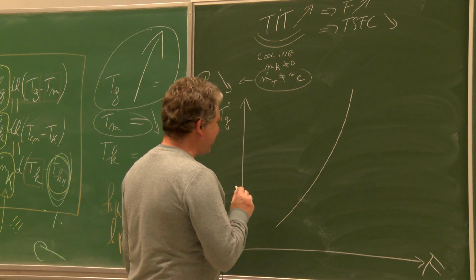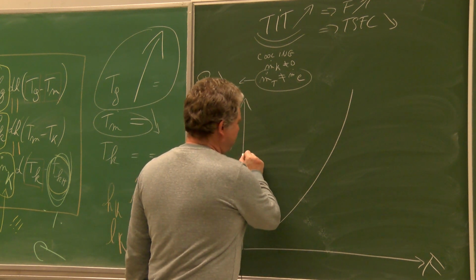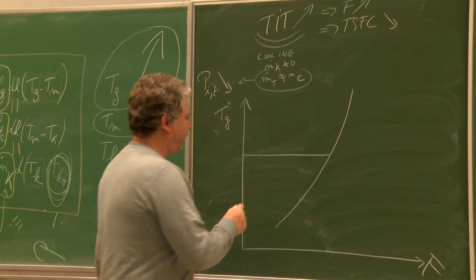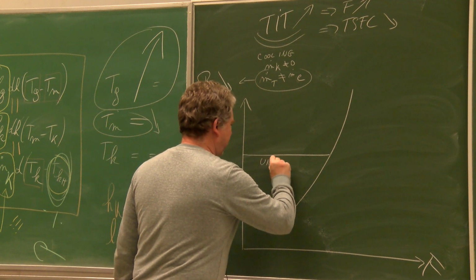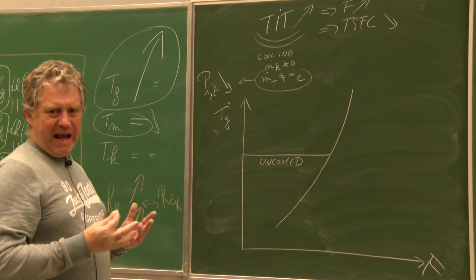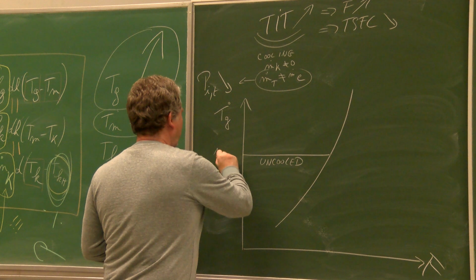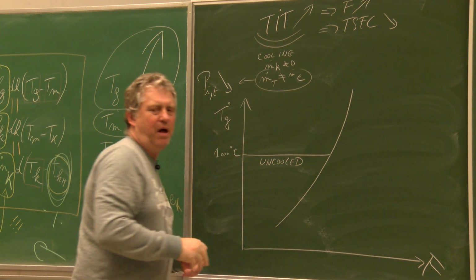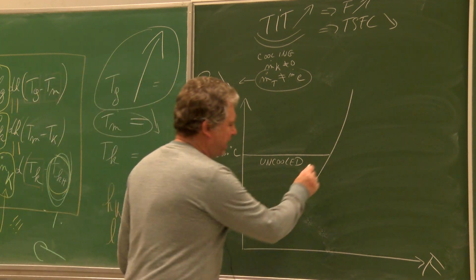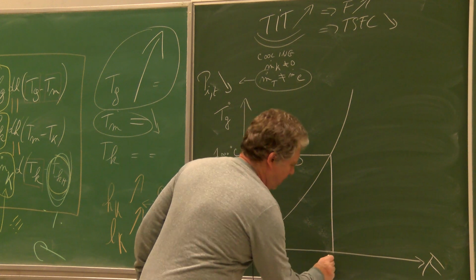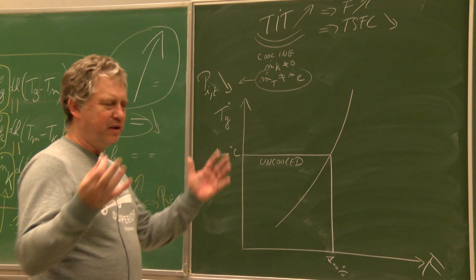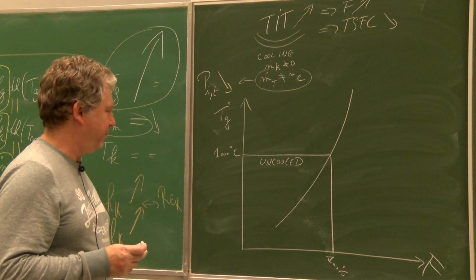But the situation is that you can have two different limits on this TIT. If you are using, let's say, an uncooled engine, you will be able to go to, let's say, 1000, in order to take an easy number, 1000 Celsius. And that is delivering you a certain thrust. Let's say 100%, whatever this value is. 1 kilonewton, 10 kilonewton, 100 kilonewton, whatever.